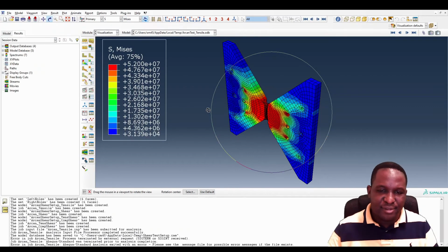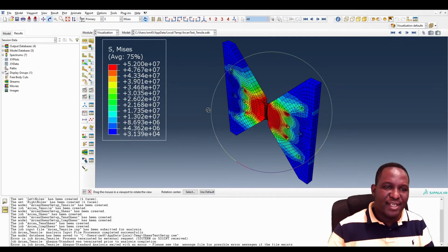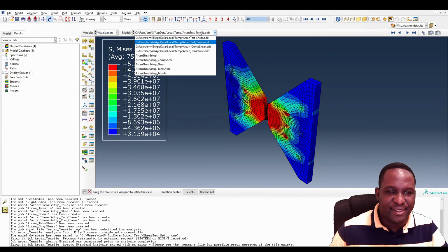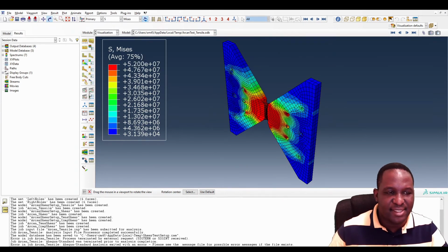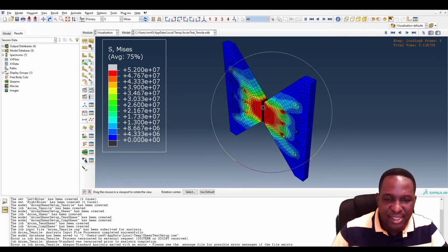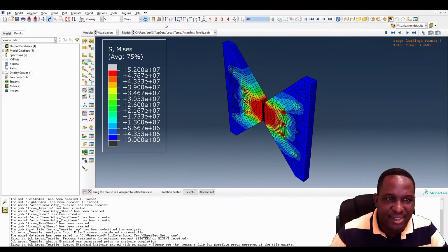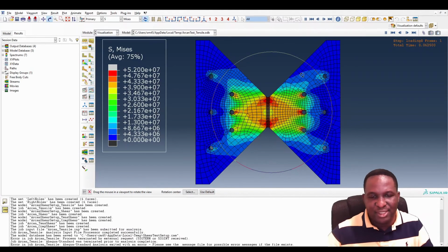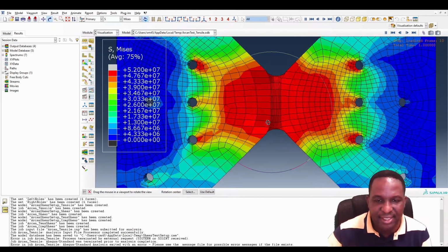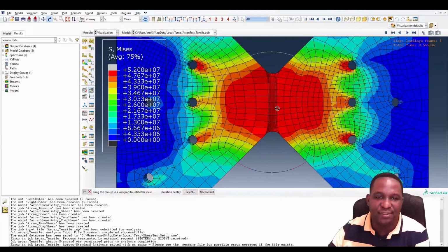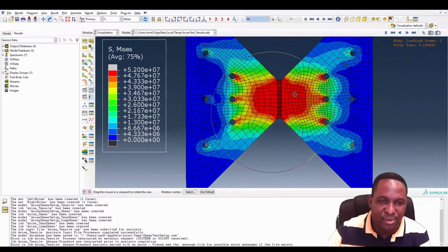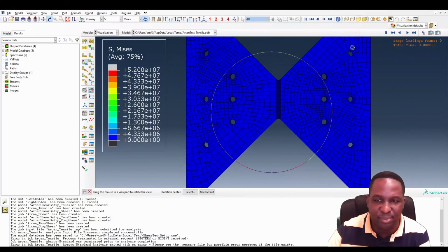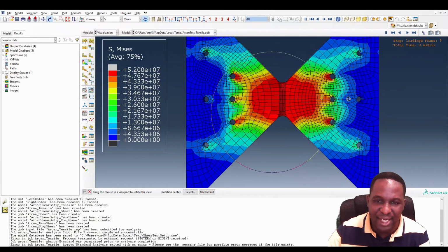Okay, so we've submitted all the jobs, they ran, and we got the simulations ready. So here is the first instance, which is a tensile test case scenario. If we do the animation of that, the specimen is being pulled in tension in a nice homogeneous way. The region in the center line here is a region where you have significant deformation. Like you know, with the Arcan Shear Test, the holes are really the points you use in holding the sample and also applying loading on the sample.